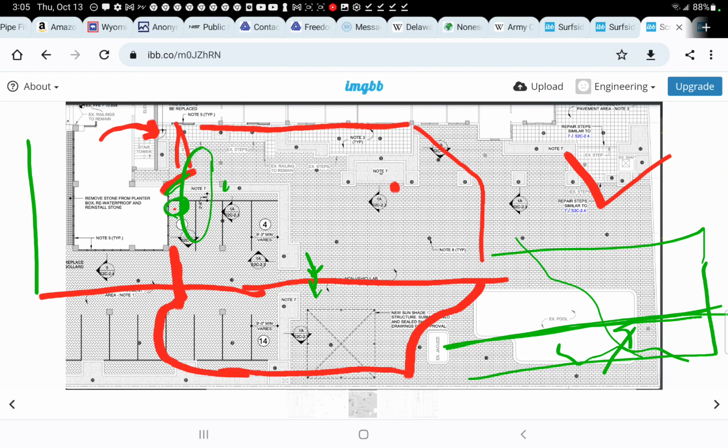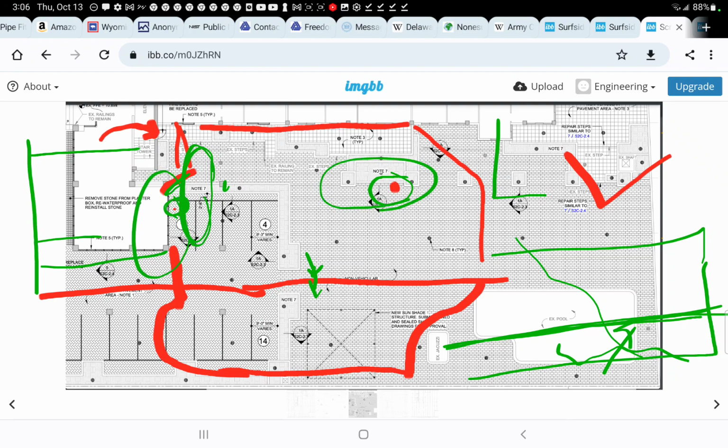There's a continuous system there. It's tied to the wall. The deflection and the area zones here create this delamination. Same thing over here. The deflection is too great. The supports or the stresses are too much with the deflection of the deck for it to hold on. It's trying to hold on with those 90s, the drop slab detail, which is here. It's even here at 11 inches, I believe. I think it's only 11 there, and maybe another foot here to gain height. It's trying to hold the deck on.